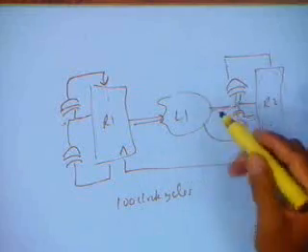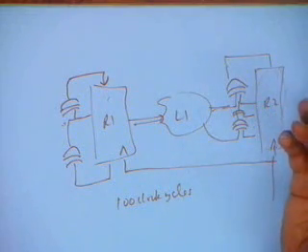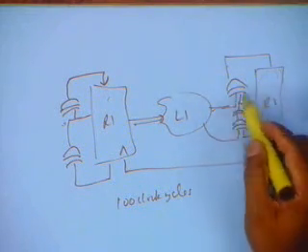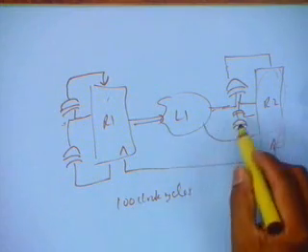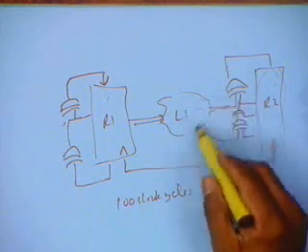If my circuit is faulty, one of these outputs has to be different for one of these 100 numbers, and once any one of them is different, then this will go into an entirely different value almost always. Okay, so there is this aliasing problem, that there may be a situation where you actually end up with the same value, but almost always you will end up with a different one.